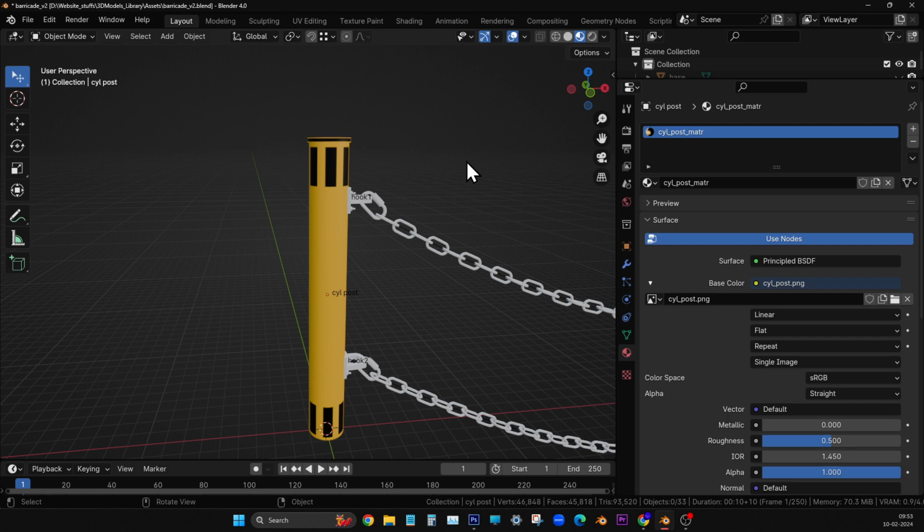Okay, maybe correct. You just come out of it. Press Z in the viewport. No, don't change the viewport. Preview. Yeah. Now you are able to see it's almost the same color, but still we want to be exact. So for that, go to the panel, and you are seeing this pick color icon, the eyedropper.